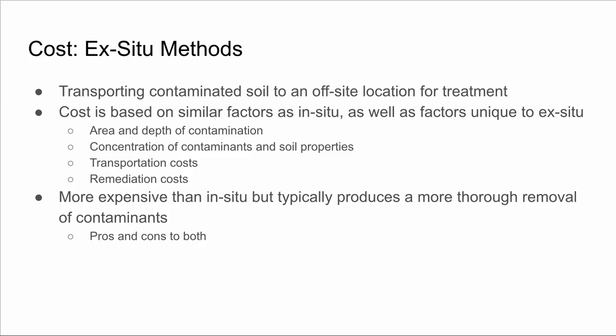You don't want to have to move it any further than you need to, so you have to take into account where is the site that you're going to be treating this dirt, how far is it from the actual remediation site. And then ex situ tends to be more disruptive to the environment, so your remediation is a little more intensive since you have to bring all the dirt back and get the site back to the same condition it was before you excavated it. So additionally, it can be more expensive than in situ, but typically produces a more thorough treatment. So there are pros and cons to both. That's just something you have to consider when you're choosing a method.